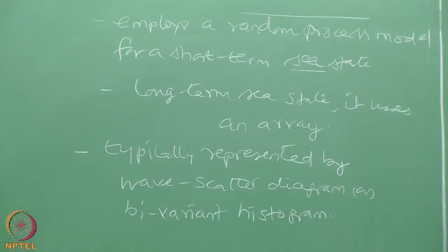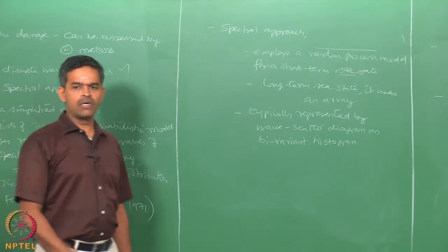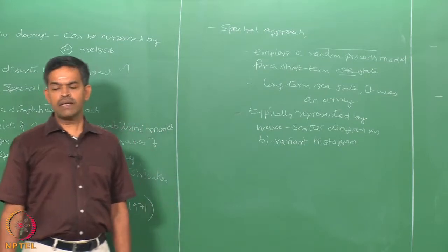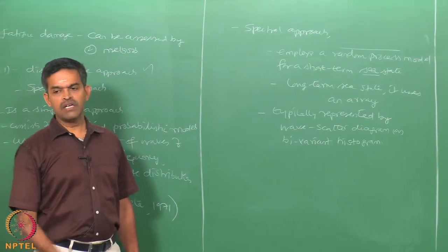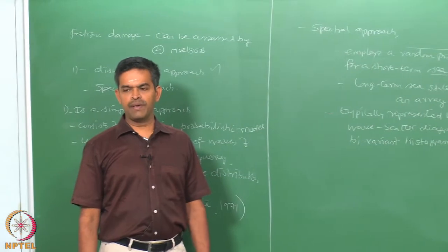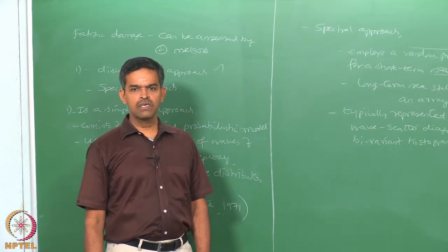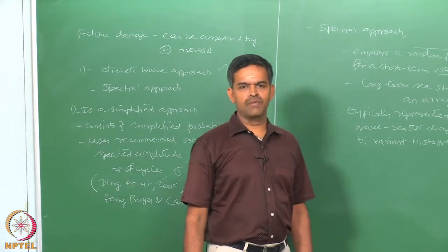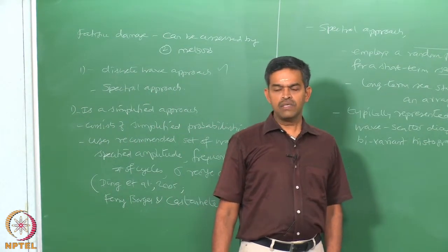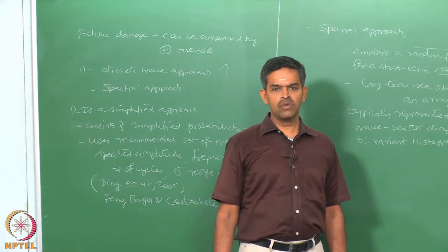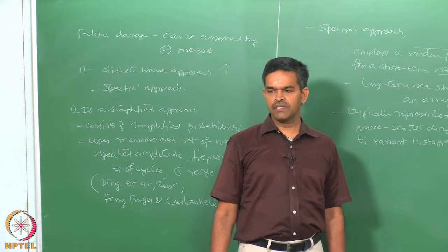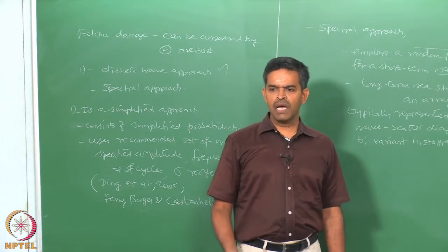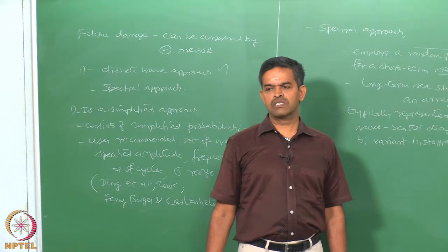We all understand and agree that the predominant load acting on offshore structures is wave loads. Cyclic stresses caused by these kind of loads induce fatigue damage in offshore structural members, especially at the tubular joints of steel jackets and towers. Since they have very high stress concentration zones, the fatigue damage is generally aggravated by the possible dynamic amplifications caused on the structural response as well.